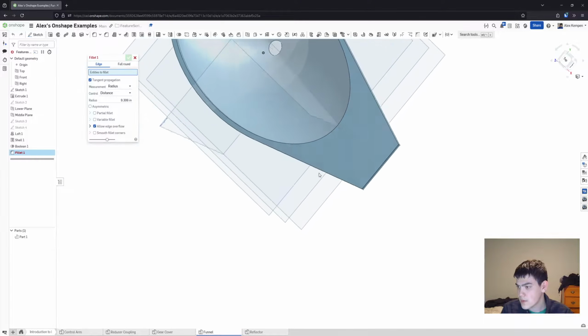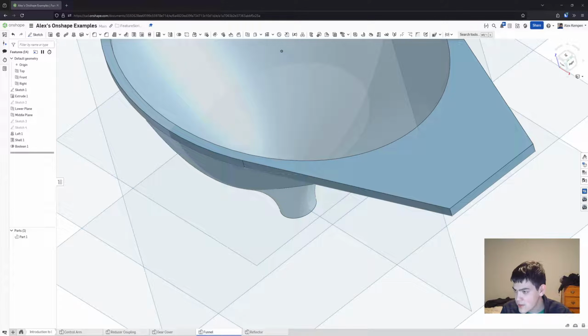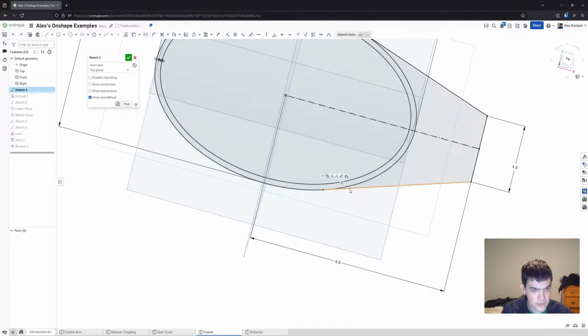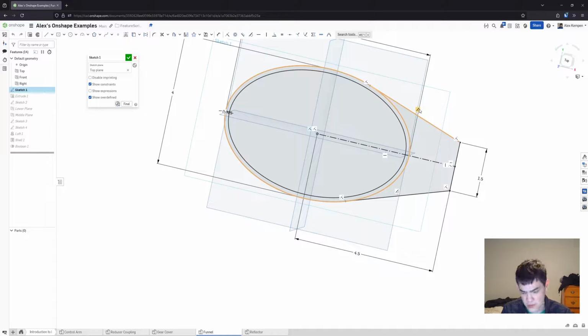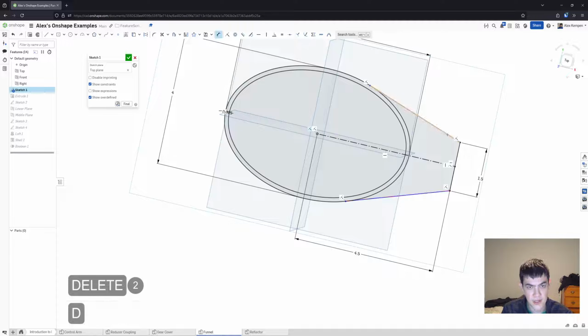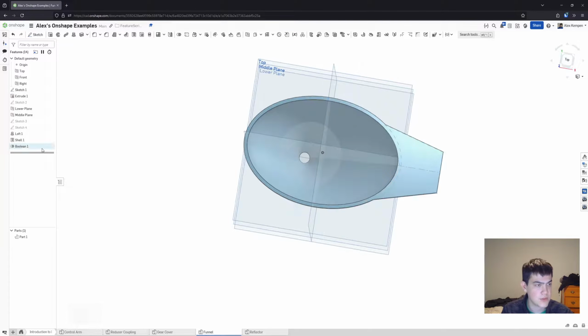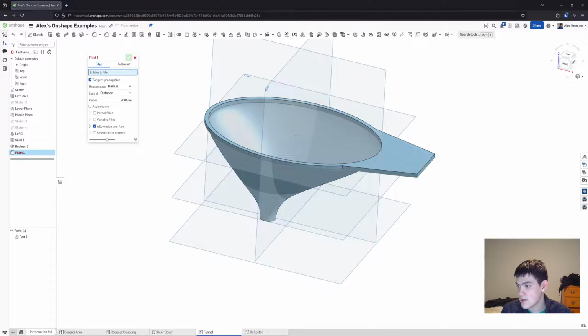Okay, cool, and then we're supposed to fillet this, and I'm noticing here this is a smooth connection, which they don't have, so I think I did something wrong. I'm going to go back and check my sketch. Yep, I sure did. I made the mistake of making these tangent, so I'll fix that. If I show constraints, I can see the tangents here that I'm not supposed to have. Instead, this is supposed to be 105 degrees, so oopsies. And then instead of adding a dimension twice, I'll just make these symmetric about the front plane. Yeah, so that works. Okay, hopefully that didn't confuse anybody.